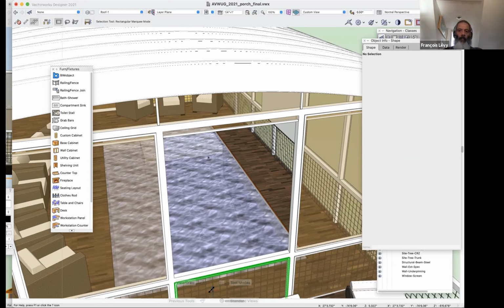And then afterwards, I saved it as a style. When you save a window as a style, absolutely every parameter of that window ends up being style defined. So then you need to go back to that window and deselect which options you want the user to be able to affect individually.